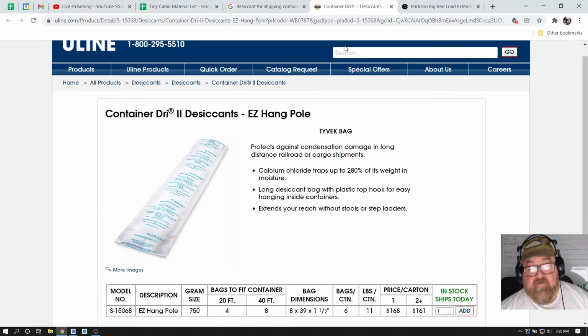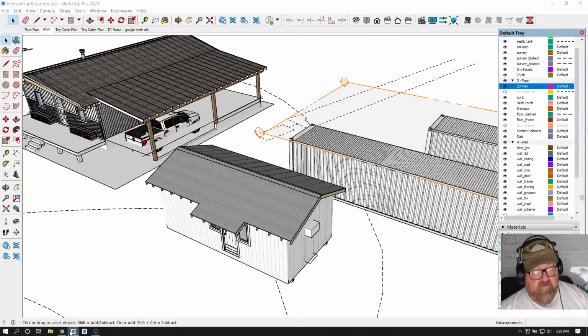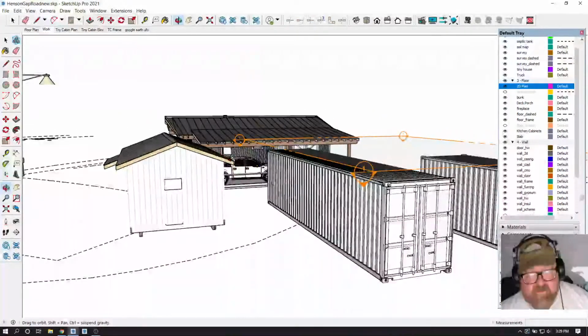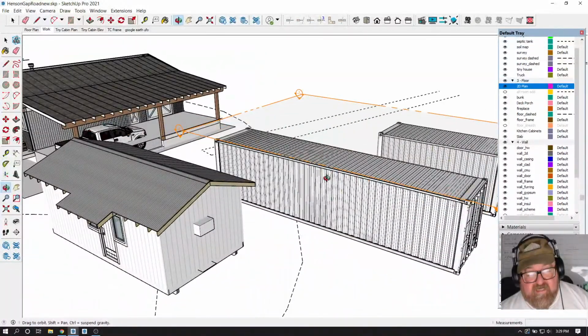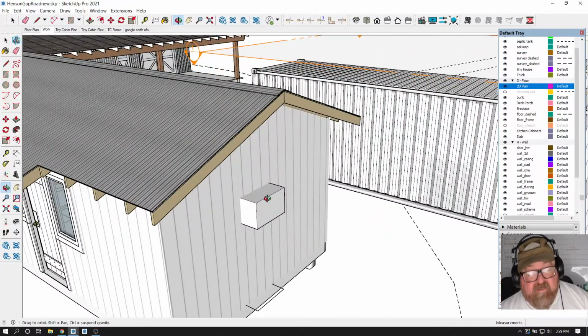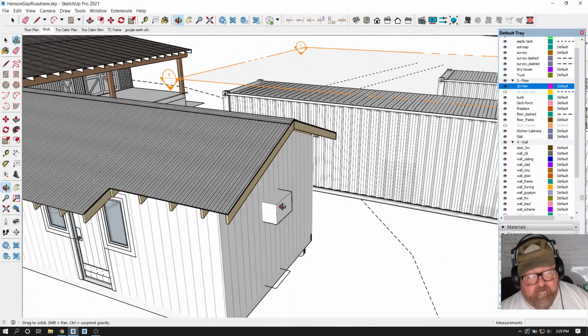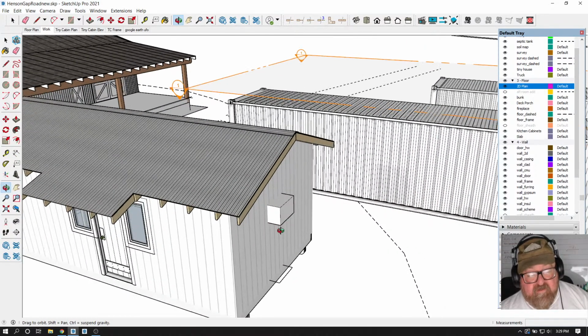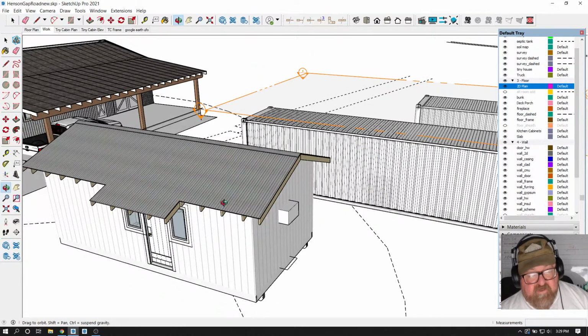The point of that is that it's a metal box, and with temperature fluctuations, it's just like this glass condensating when I've got a cold drink and it's warm in the room. It's going to collect condensation on the inside. My little through-the-wall heat pump is condensating, so it'll have a drain. In the summertime, you'll probably see a constant little flow, so I'm going to put a little pile of gravel out here because of that. So I'll be taking the moisture out of mine.